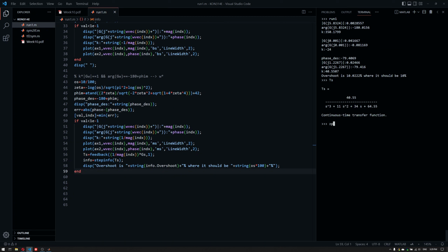And if we look at the closed loop here, we can see that due to the third order system, we have the second order part. Maybe if this pole didn't exist, this would give us a solution at phi m, but we needed to shift it a little bit due to the third order system here. So what is the roots of 1, 3.338, 8.425? So it's basically this here.